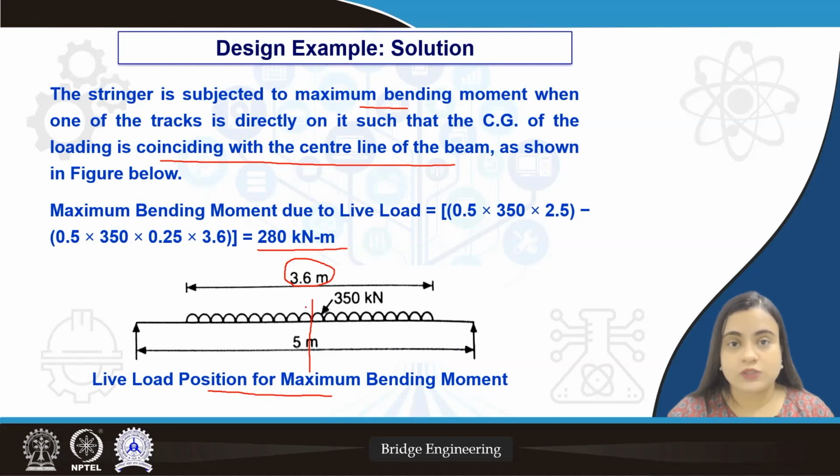If we are not able to memorize the formula involved, please do it from first principles. That is always useful because we can first have the loading diagram ready, then we can go for drawing the shear force diagram, and the area of the shear force diagram will give us the bending moment diagram. From there, once we draw the bending moment diagram, we will be able to identify the maximum bending moment.